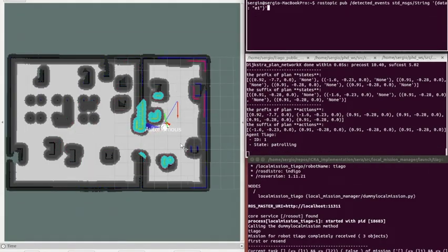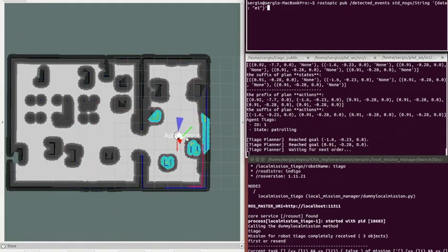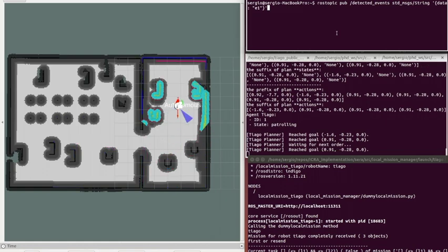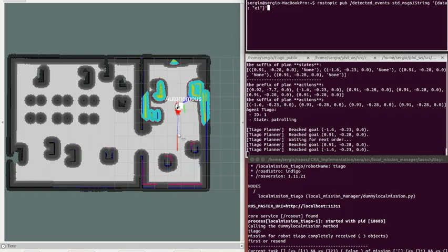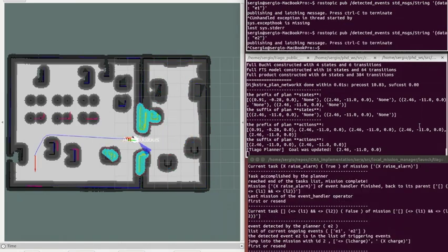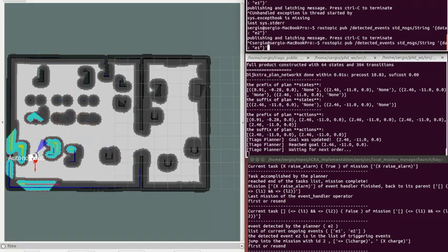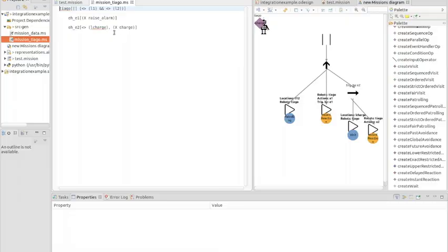When the textual syntax is saved, an intermediate LTL-based language is automatically generated. It is a formal representation of the mission the robot should achieve. It is not intended to be read by humans since it is sent to each robot, where an interpreter parses it and applies the semantics of each operator.